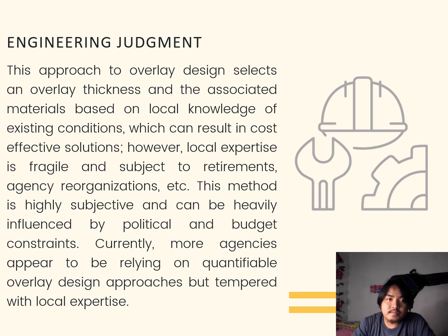First is engineering judgment. This approach to overlay design selects an overlay technique and associated material based on local knowledge of existing conditions, which can result in a cost-effective solution. However, local expertise is fragile and subject to retirements, agency reorganizations, etc. This method is highly subjective and can be heavily influenced by political and budget constraints. Currently, more agencies appear to be relying on quantifiable overlay design approaches but tempered with local expertise.